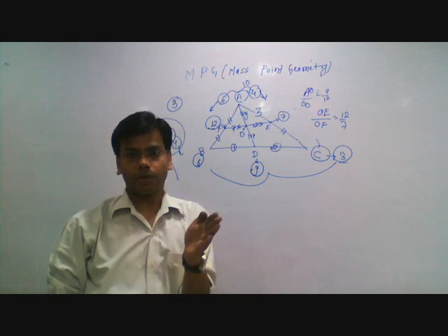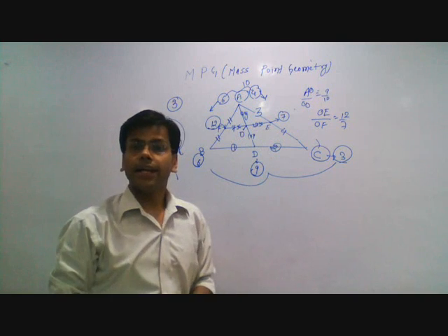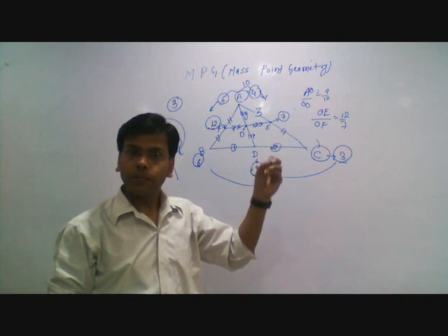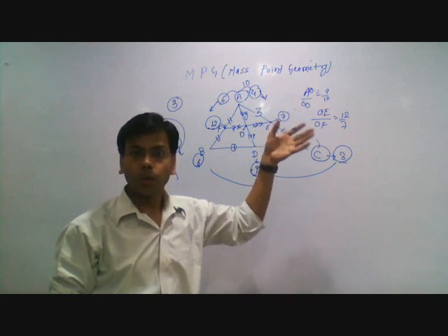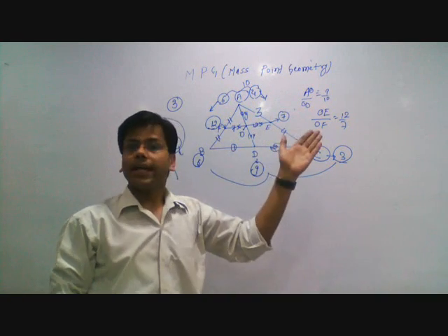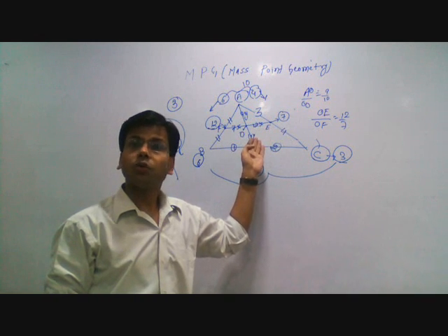And cross-checking for the value, are you on the right track or not? Work on line AD. Calculate the weight at O. 10 plus 9 is 19, just addition at O in the line AD. Work on line FE. You have 12 and 7, so the weight on O should be 19.